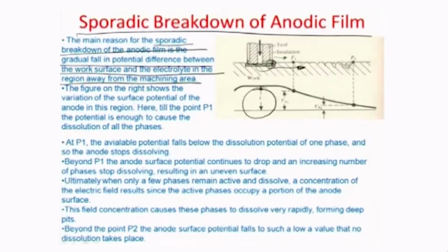So, for example, if this is the particular potential function which is available to this surface, it slowly goes down as the distance increases as a square of r, but there does exist some value here. For example, at the point P1 it may be Vp1, at the point P2 it may be Vp2, and so on and so forth. So, there are some finitely existing values of the fields which escape even though the tool is placed at some distance away from the surface. This is all covered with electrolyte, because naturally the electrolyte flows around this gap and flows over the surface and everywhere else, and it flows into the tool from this entry point here in the center.